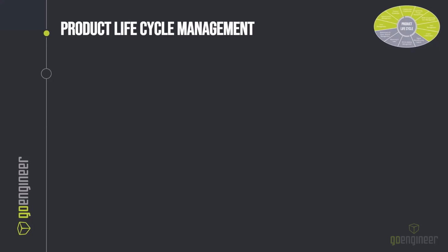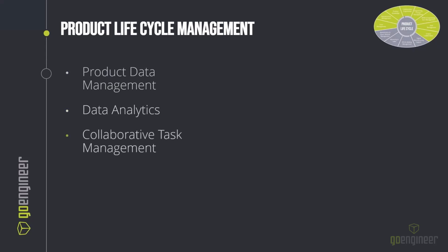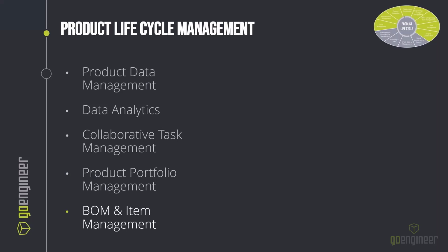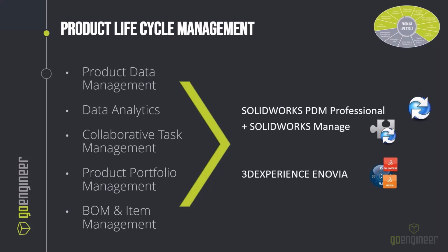And for a robust PLM system, we need PDM functionality, we need information and analysis about our data, the ability to create and track real-time work, a way to manage overall portfolio of products, and streamlined management for BOMs and non-CAD items. So in the Dassault family of solutions, this would be PDM Professional with SOLIDWORKS Manage, or SOLIDWORKS with a connection to the 3DEXPERIENCE, leveraging higher level ENOVIA functionality.